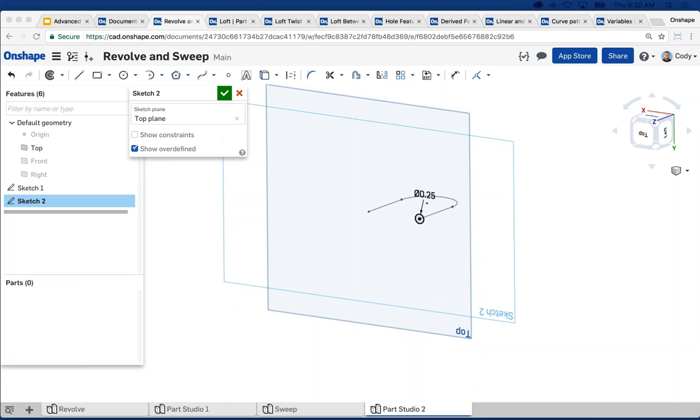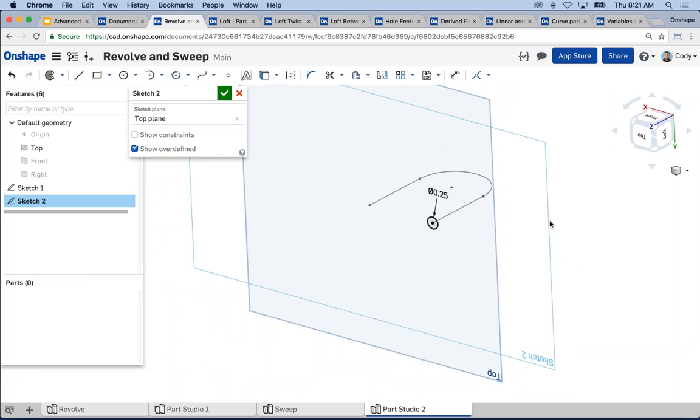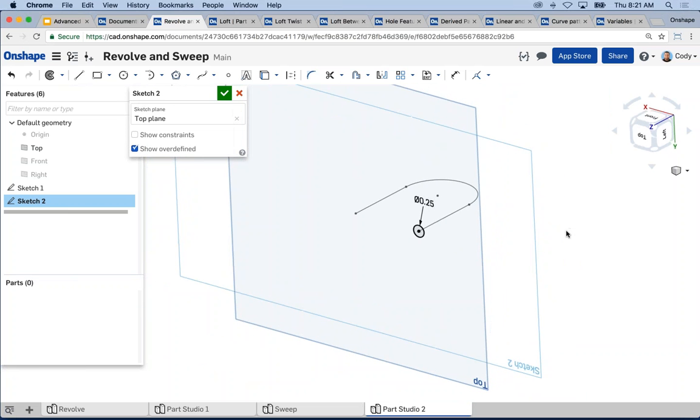Is pierce particularly special compared with coincident? Well, remember that coincident may not always be there. For instance, if I wanted to attach this circle to a spline that goes through several different planes, then I wouldn't have coincident as an option. Pierce would be my only option. Right? So in certain situations, pierce will be necessary, but think of pierce as where that curve that you're selecting pierces the current sketch plane. That's what a pierce constraint is.